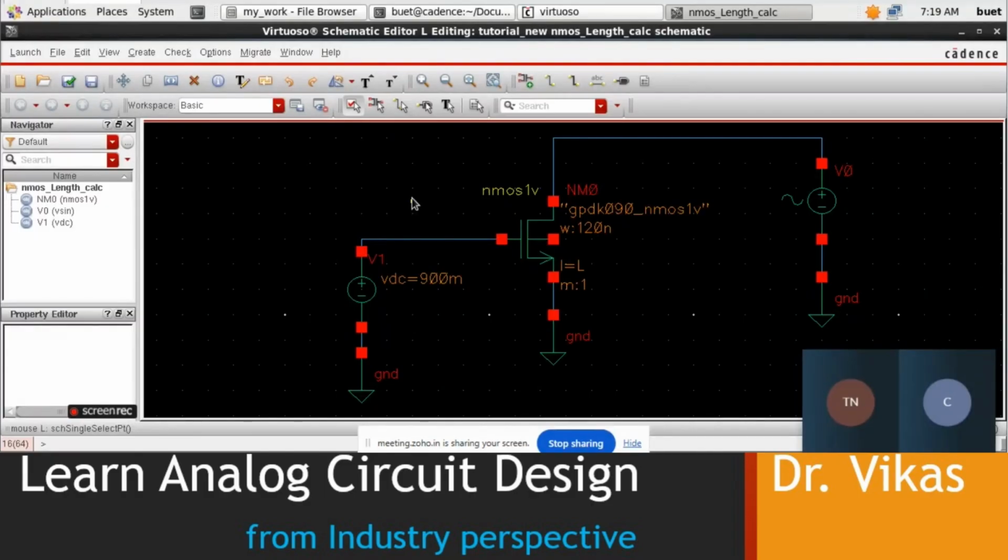The condition is the output resistance of any current source. The resistance of that particular current source must be as high as possible practically speaking, or in idealistic terms, the output resistance of my current source should ideally be infinite. So if I want to build a current source, then that current source's output resistance has to be very, very large.